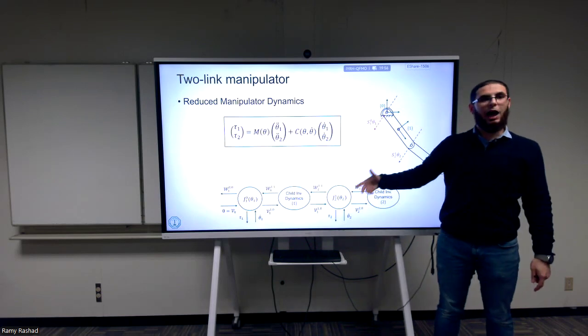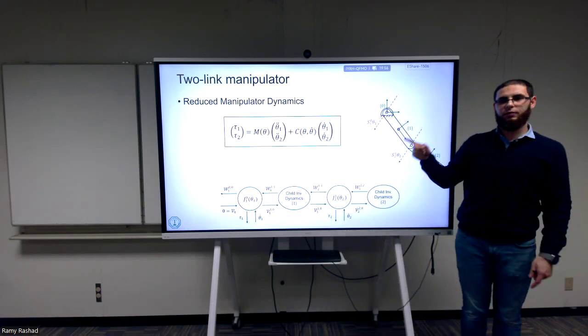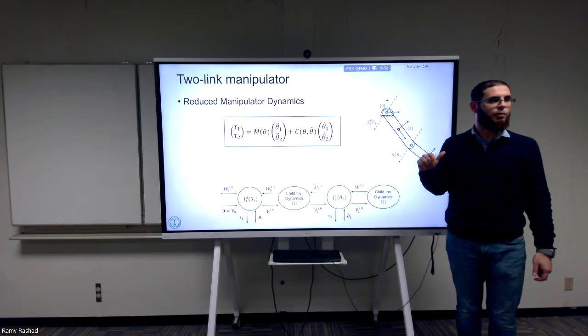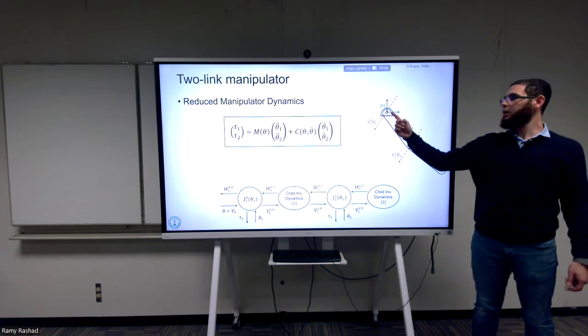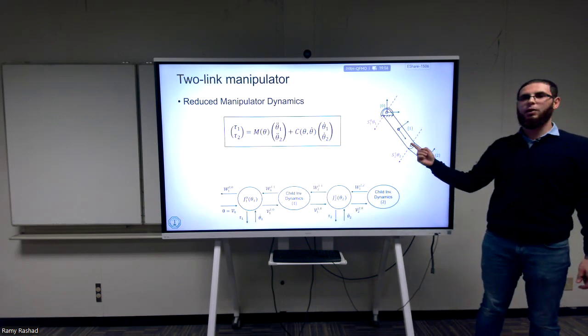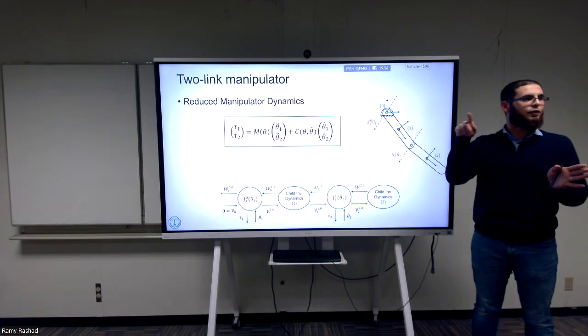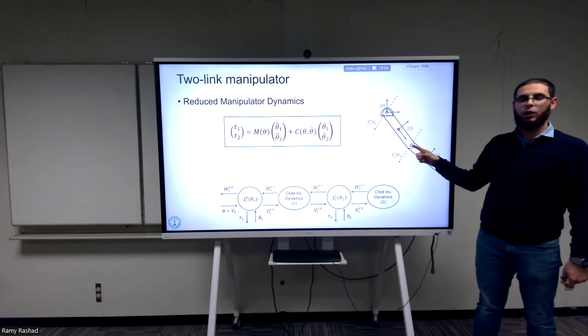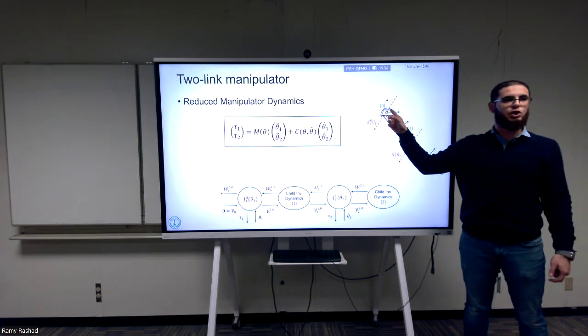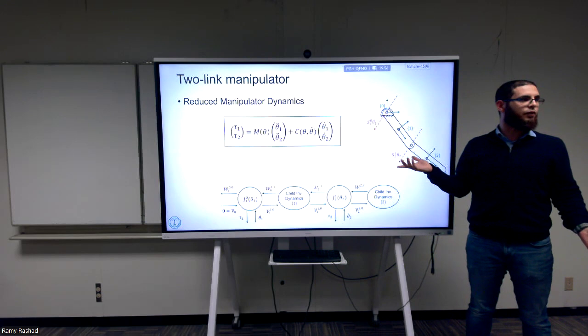But in the end, how many degrees of freedom does this system have? Let's do the calculation of last time, if you remember. We have here 6 degrees of freedom and one joint, 6 degrees of freedom and one joint. So how many total degrees of freedom? I have 12, and then this joint reduces 5, and this joint reduces 5. So in total, how many degrees of freedom?